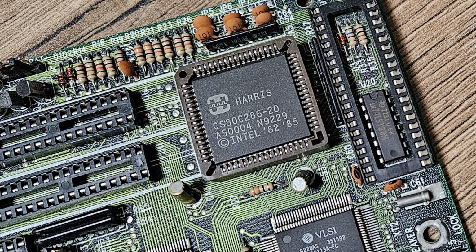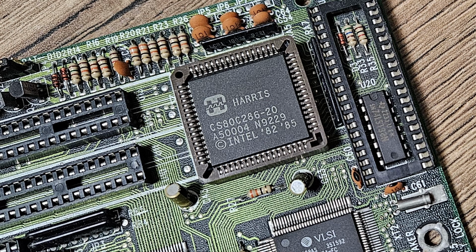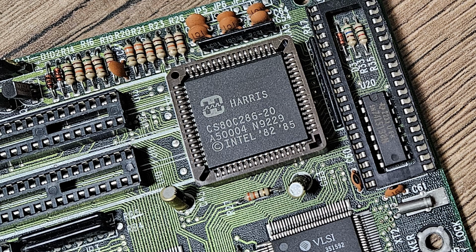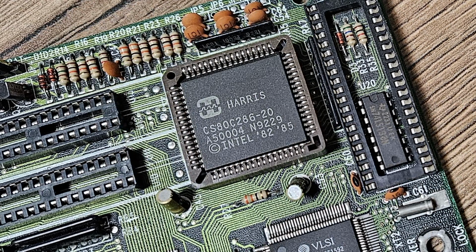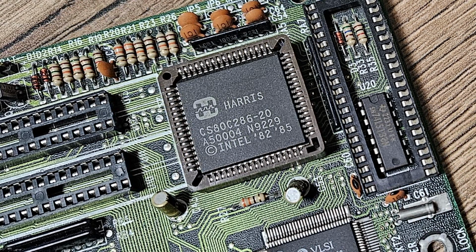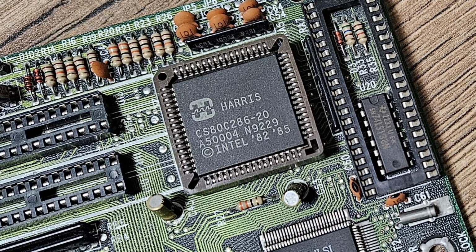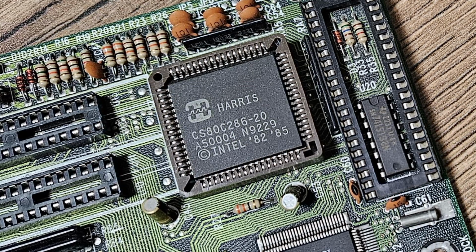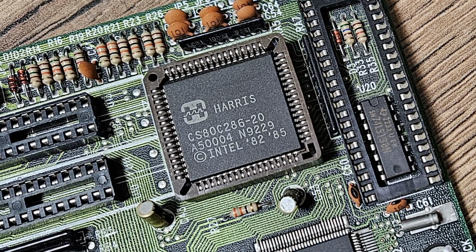The 286 had two important features. The first one was on the hardware side, so it dropped the multiplexed bus. It was easier to use in circuits because there were no need to use additional buffer ICs. The other feature was on the addressing. It was able to use 24-bit address bus if it was switched to the protected mode. The protected mode was introduced to make easier the life of the developers when they are developing something like a Unix operating system, but the protected mode was not really compatible with the original PC. The next Intel CPU, the 386, corrected these problems, but we will get there later on.